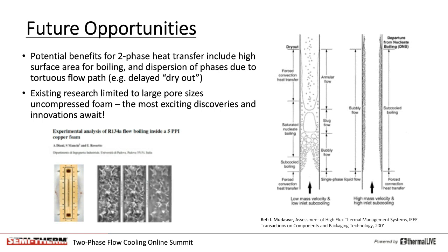In pool boiling and high mass flux flow boiling, such as in pumped two-phase systems, this phenomenon is referred to as departure from nucleate boiling and can quickly result in overheating of the component being cooled. Meanwhile, in vapor cycle systems that must evaporate virtually all liquid prior to compression, the term dryout is used to denote liquid film dryout in annular flows that occur toward the end of the evaporator.